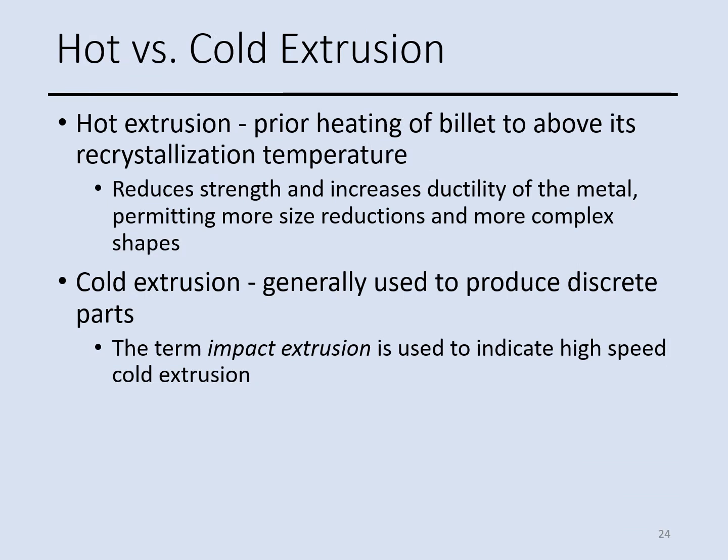The extrusion process can be performed at a hot temperature or a cold temperature, and it depends on the work metal and the amount of strain that we need during the formation. For example, aluminum, zinc, magnesium. These are some metals for which hot extrusion is preferred over cold extrusion.